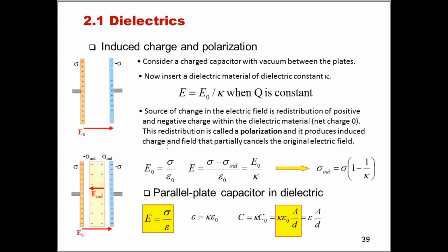So going back to the parallel plate capacitor in presence of a dielectric material, we just demonstrated that we can again write the electric field using a form that is very similar to this, but simply now we have to replace epsilon 0 with epsilon. So epsilon is the dielectric constant of the material, given by this formula: epsilon equals K, the relative dielectric constant, times epsilon 0.